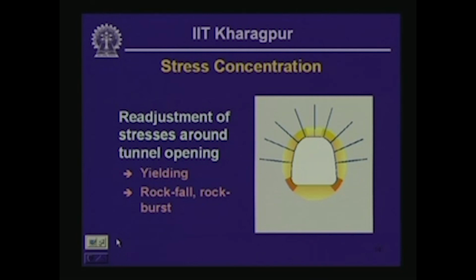Okay. Stress concentration is another issue that should be tackled while designing a tunnel. Readjustment of stresses around a tunnel opening, over and above its background value which developed because of geologic processes, may lead to yielding, rock fall and rock burst. We discussed these topics previously, so I am not going to get into the details right now.